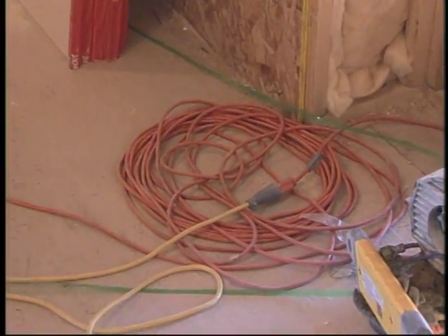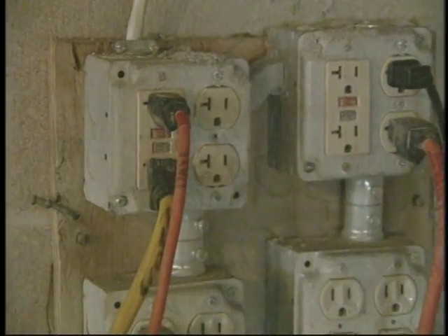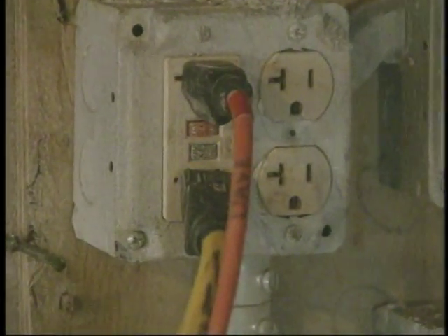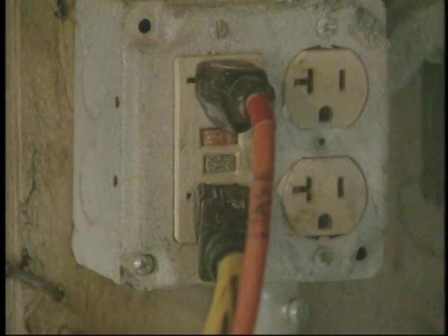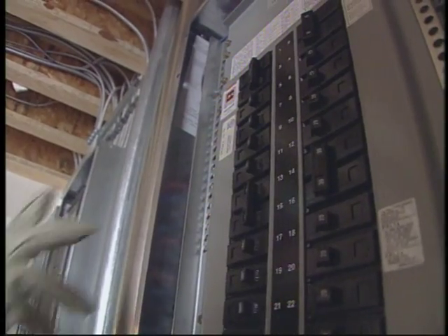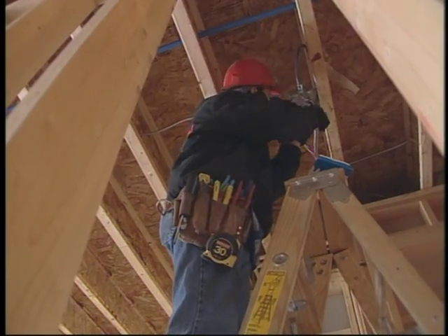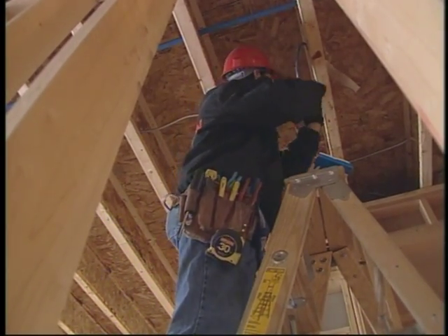To avoid accidents, your first protection is to make sure your electricity is properly grounded. This means creating a safe path for it, away from your body, and containing it within the equipment or tool you're using. Fuses and circuit breakers help protect cords and equipment, while ground fault circuit interrupters, or GFCIs, protect people. GFCIs are required on all temporary power at construction job sites. Fuses, circuit breakers, and GFCIs should be checked regularly. Also inspect end terminals, splices, and screws to make sure that they're not broken or loose.